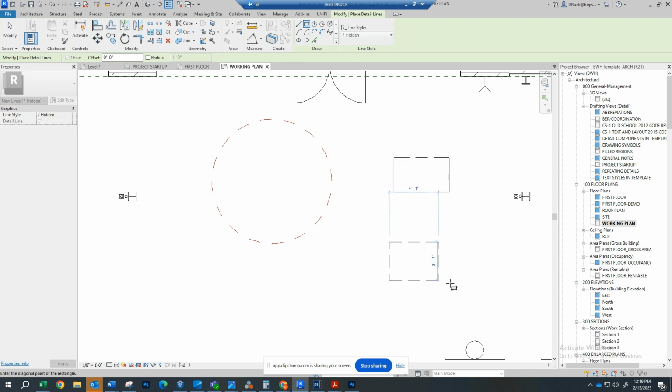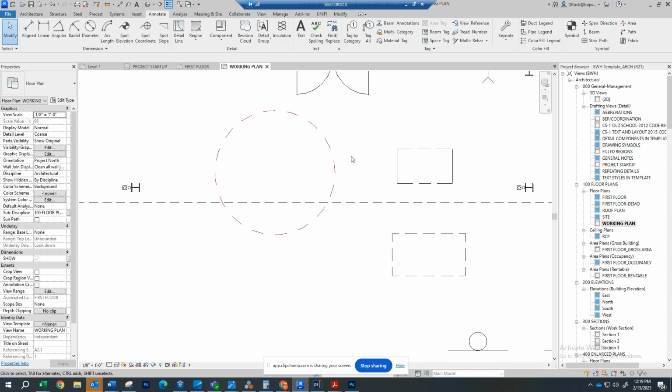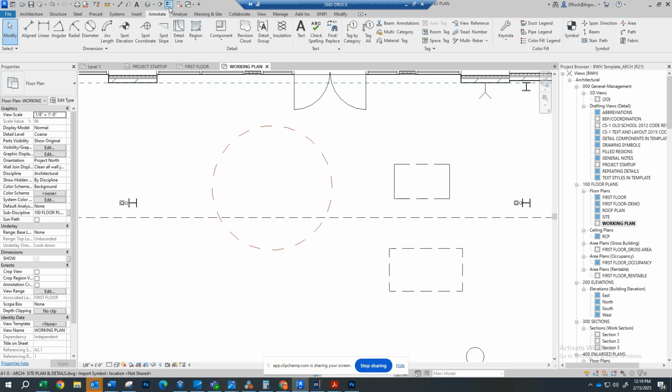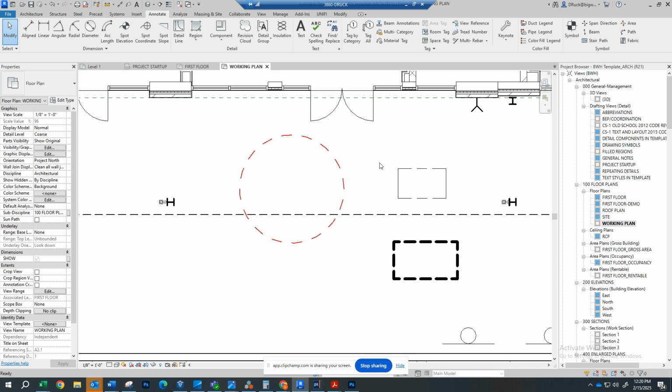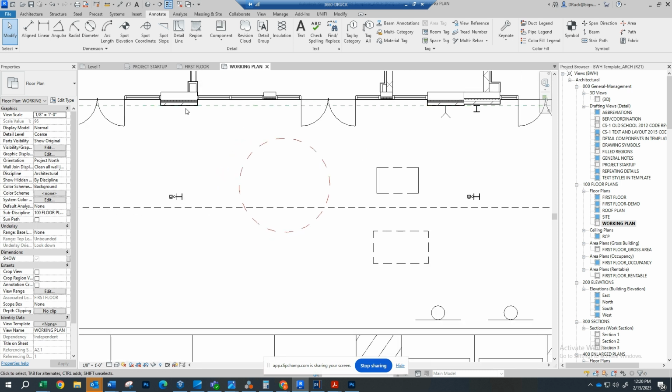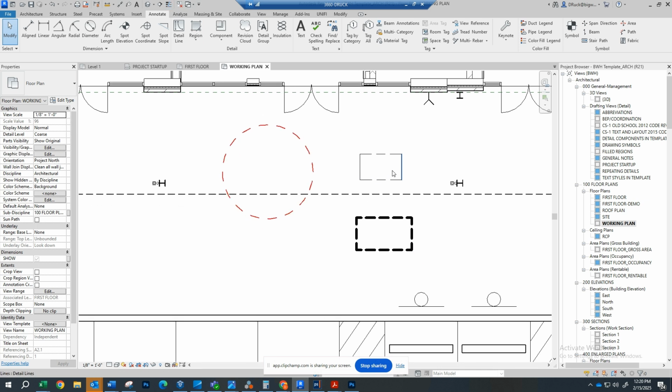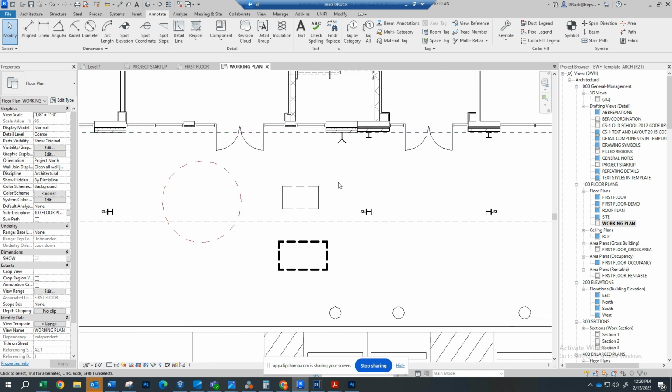So if I draw this, they all are appearing the same right now. There's the little tool called thin lines all the way up at the top. If you check or uncheck it, you will be able to see the thickness of the lines graphically now. I personally like to draft in thin lines, and then before I print or before I'm done working in a view, I'll uncheck it to make sure that visibly it's appearing the way I want it to.